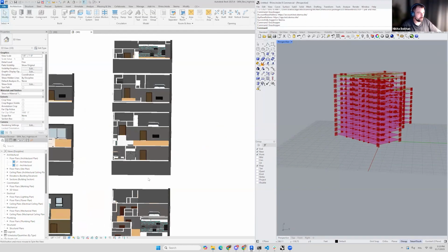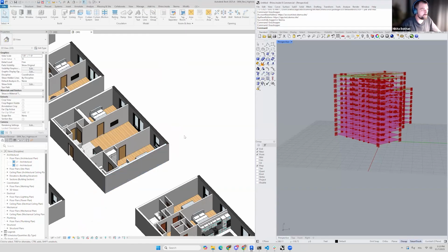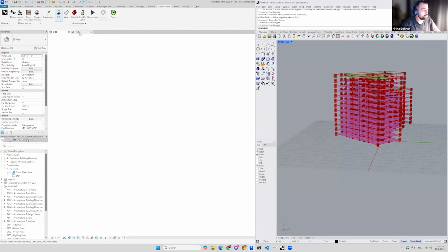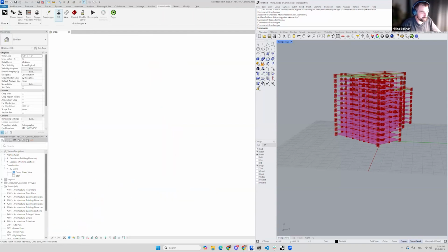But in some cases, a demising wall might become exterior. In that case, it will be a general external wall, not an external unit wall. We did it because in some cases a user wants to separate them, and, let's say, create one type of facade for the edge cases and another type of facade for the walls where the windows are located. We might have the same, but it's up to us how to proceed with it.